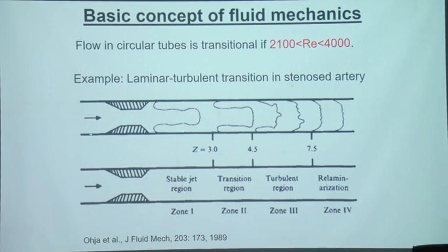They're trying to quantify, visualizing flow in the channel downstream of this narrowing. Because of this contraction in area, even though the flow enters the channel as laminar, when it passes through the narrowed section, the flow starts to accelerate and creates a jet.